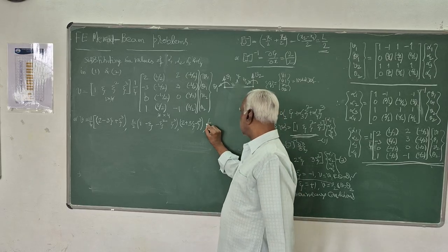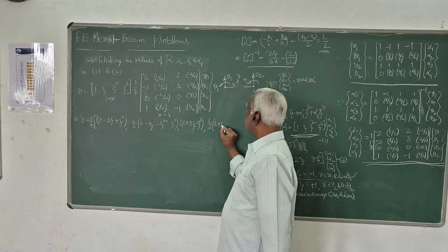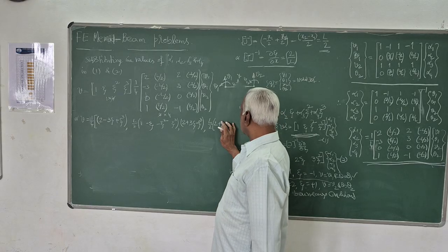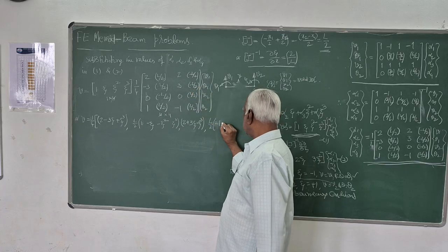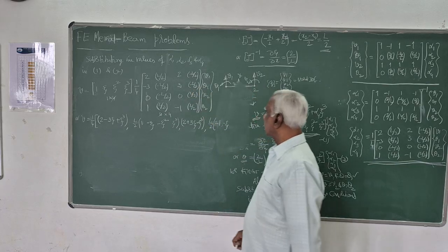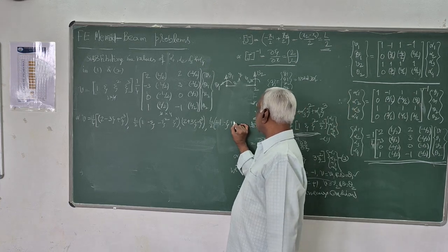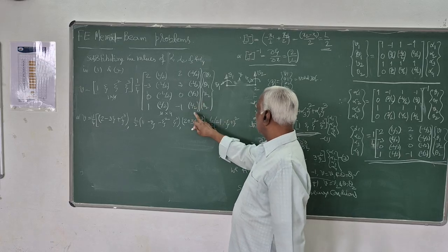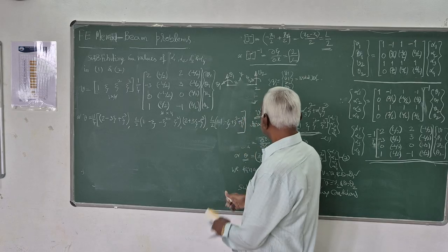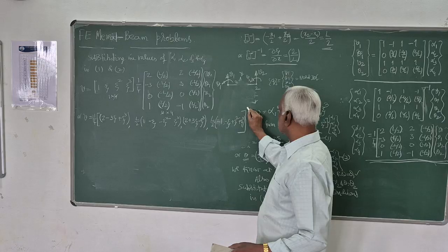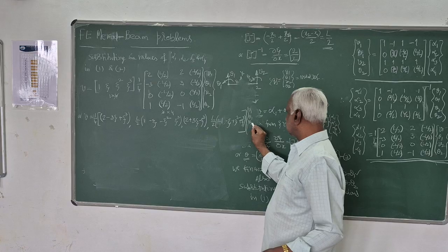And lastly, this will be L by 2 into, not 2 plus 3 psi, it is 2 into minus 1, then psi minus 1, minus psi, minus plus psi square, plus psi cube, into, of course, the nodal displacements V1, theta 1, V2, theta 2.